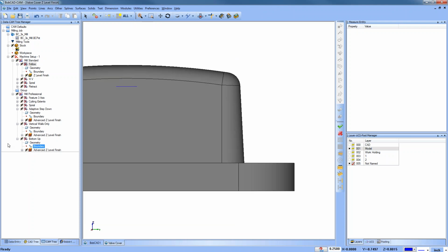Okay. Does anybody know the weakness of Z-level finish? If there was one kryptonite for Z-level finish, do you know what it is? If you do, go ahead and raise your hand. Or if you have a microphone and you do, go ahead and raise your hand. No undercut. Yeah, actually, you can do undercutting with Z-level finish in Mill Pro and Mill Premium. Anybody else? Anybody know the kryptonite for Z-level finish? Reginald says he knows. Richard said a flat surface. Actually, no, a flat surface. Well, I guess depending.